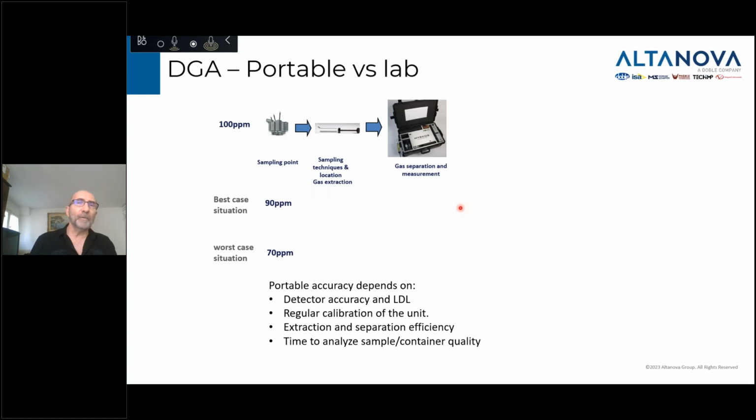Now, when you look at other ways of doing DGA: since 1965, mostly the whole world has done annual or semi-annual punctual DGA. Over the last 20 years, technology has also brought portable DGA equipment. The advantage is a much shorter line of doing the DGA. You go directly to the transformer's drain valves, take your sample, and right on the spot, you can do your DGA.